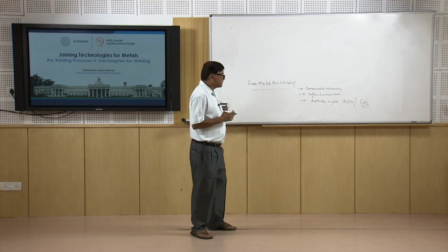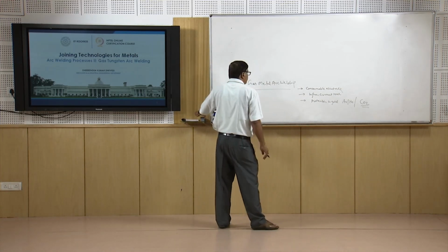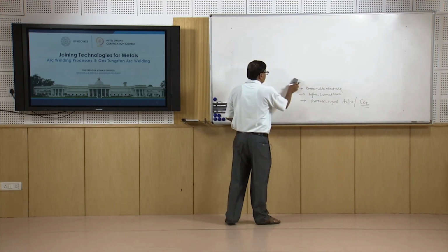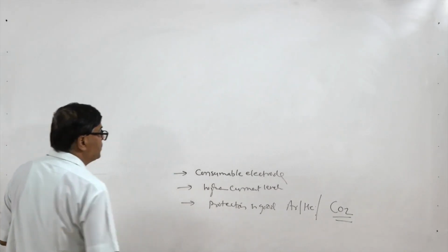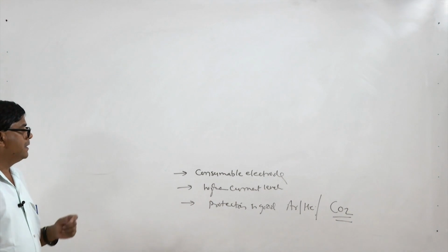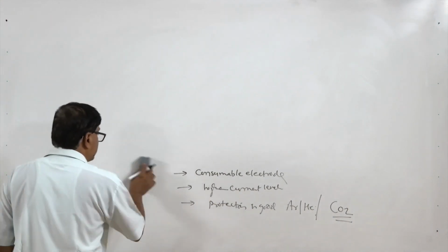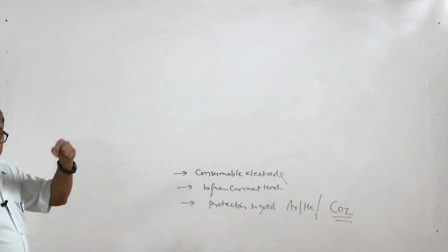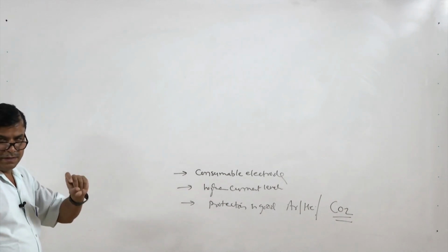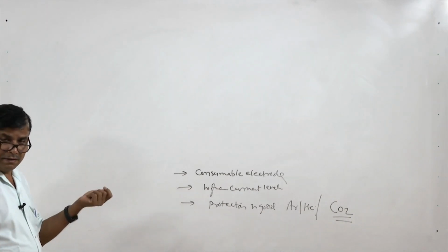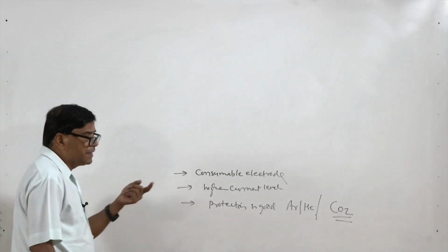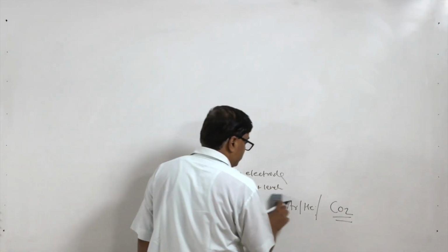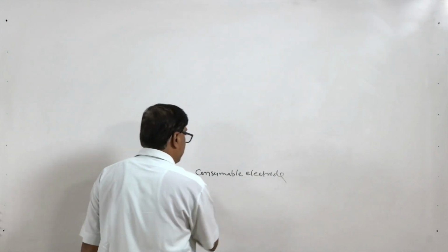of other gases like argon modified with oxygen, argon with carbon dioxide, or helium and argon mixtures. Various combinations of gases are also used, since this process is different from the gas tungsten arc welding process in the sense that it uses a consumable electrode. It uses gases like argon, helium, argon with oxygen, argon with hydrogen, a helium-argon mixture, or CO2 with argon. So, various gases are used, and as this is not limited to inert gases, even inactive gases are also used in the gas metal arc welding process.